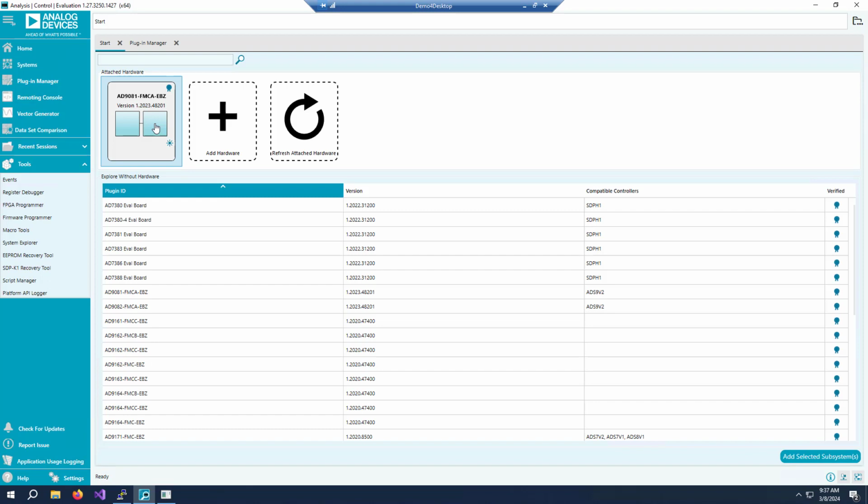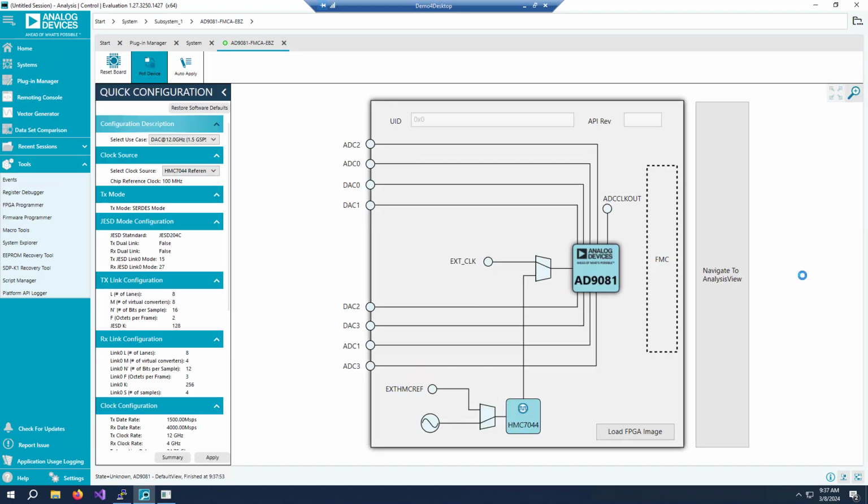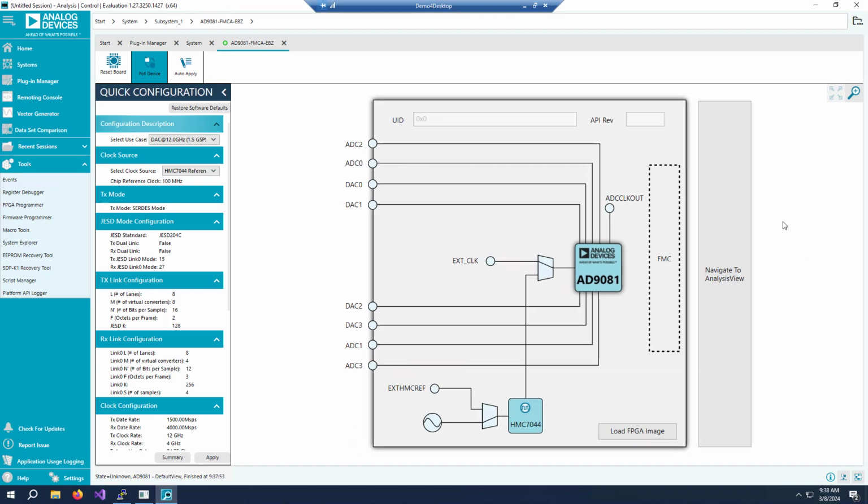But once it does find it, you double click on what it found and it brings up the board. And I'm going to wait. You can see the spinning cursor here. I'm going to wait for just a second, and here's the configuration. One very important thing to know that this is really working is that this field right up here gets populated with some big honkin' number. If that says 0x0, then it's not really finding your chip and hardware and things like that.